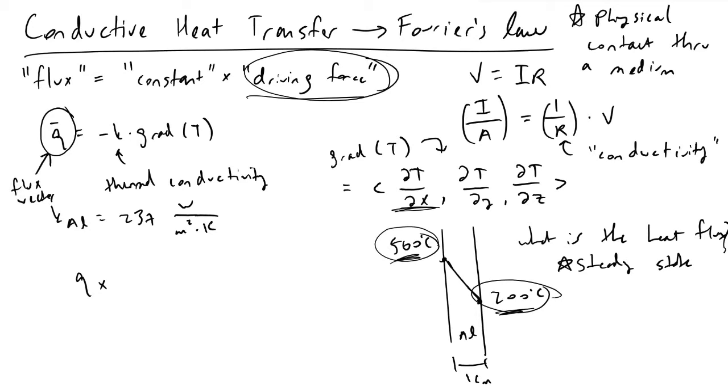that you're interested in. And so what we have to do is make our assumptions, and this is something that they like to nail people on at Berkeley with their exams: state your assumptions. We're going to be operating at a steady state, and in this case we're working with aluminum. I've already defined what our thermal conductivity is for aluminum, and so actually determining what the heat flux is through this material is pretty straightforward.